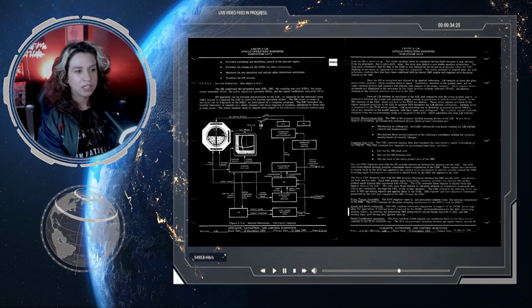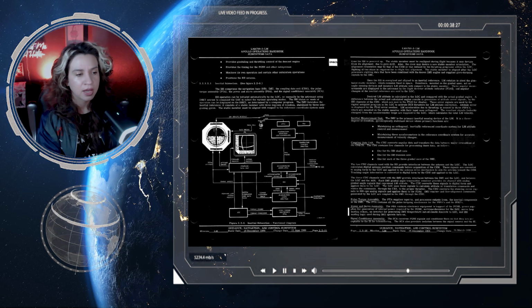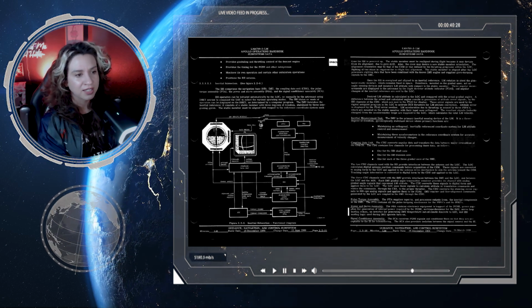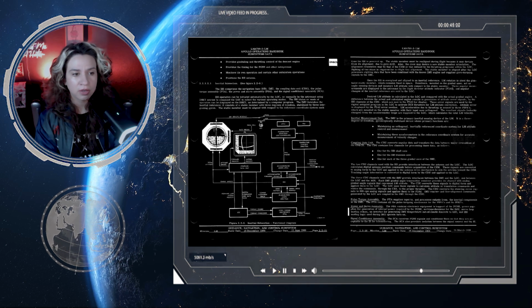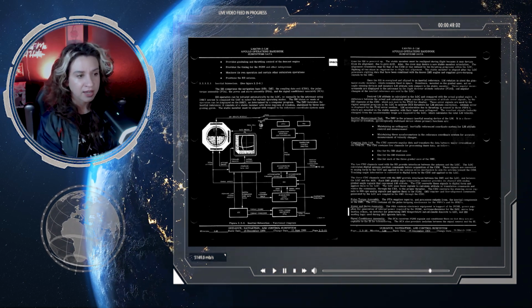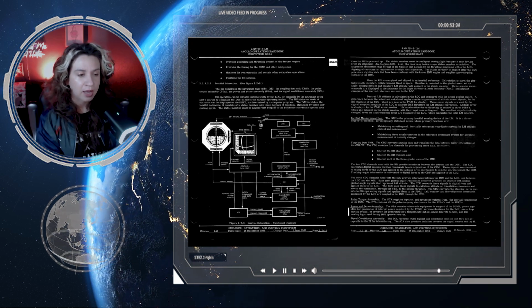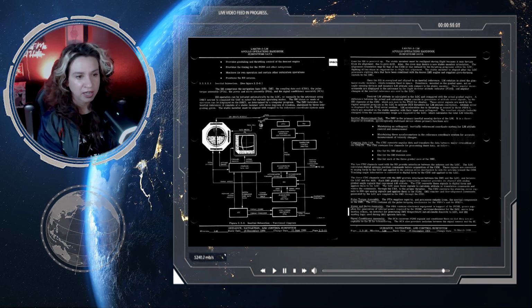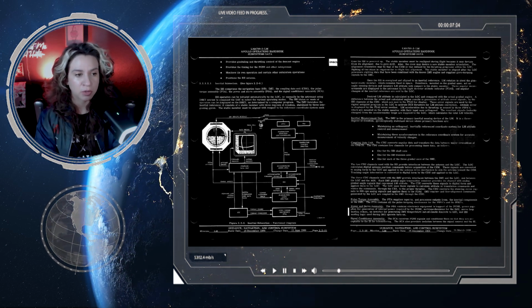The LGC uses these signals to calculate attitude and translation commands and routes the commands through the CES to the proper thrusters. The CDU converts the steering error signals to 800 CPS analog signals and applies them to the FDAI. IMU coarse and fine alignment commands generated by the LGC are coupled to the IMU through the CDU.